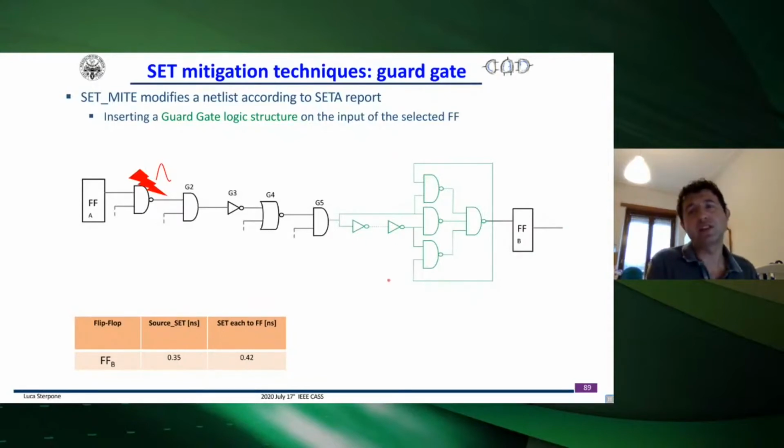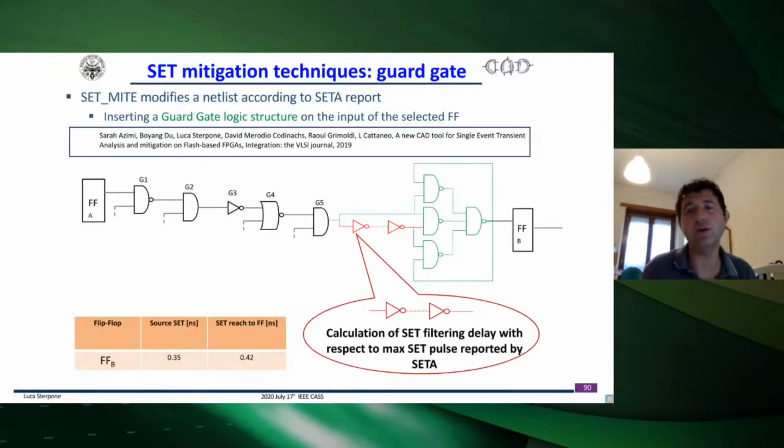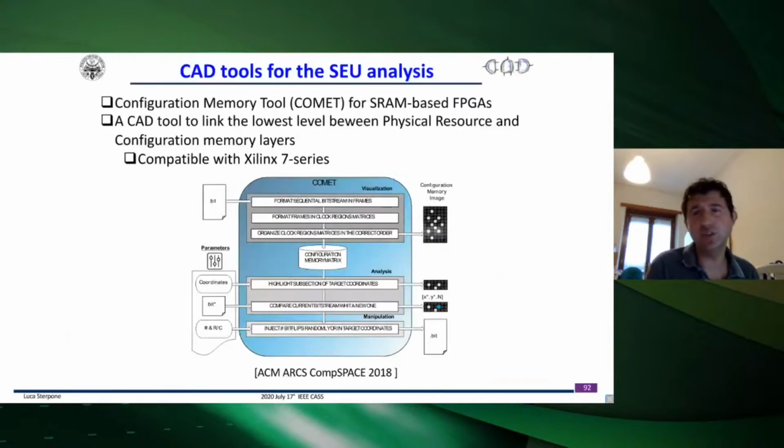That's how the mitigation works, exactly here. There is a good picture to show you that the pulse traverses the gate, reaches this filtering, and then here it is nullified. And you no longer have the transient going into the flip-flop. That is good because you can put this implementation in place. But then here we have a lot of things to be placed together.